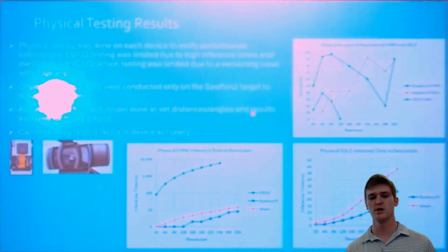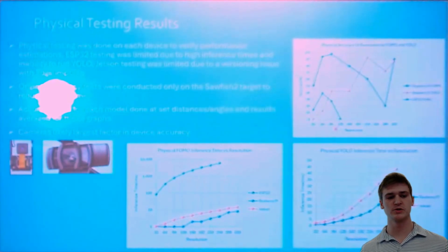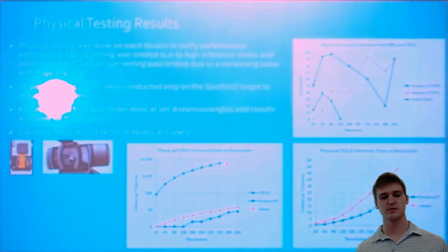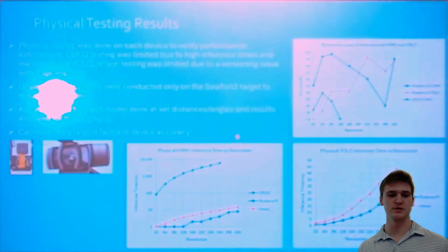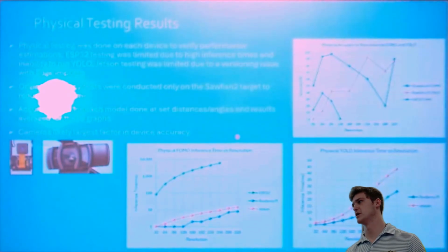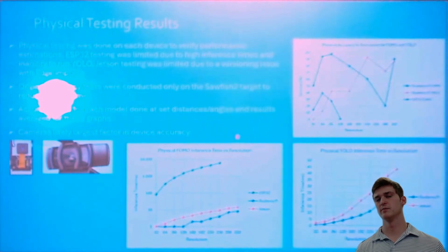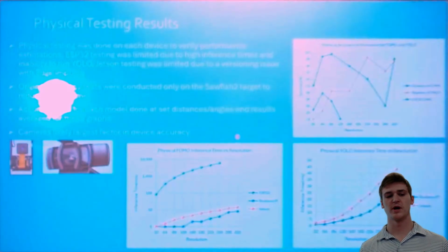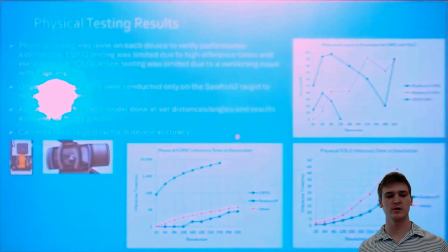up on these tests. So I was only able to test up to 128 resolution for the ESP32, and it was unable to run YOLO models, as well as not being able to run models bigger than the 256 resolution here for inference time. And the Jetson was limited due to a versioning issue with Edge Impulse that didn't enable me to use the command line interface for accuracy testing, but I was able to use a Python SDK method for the inference times test for it.